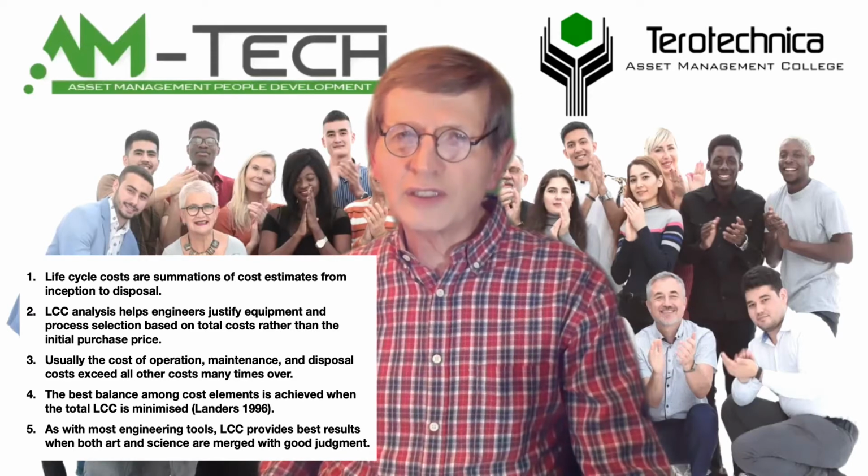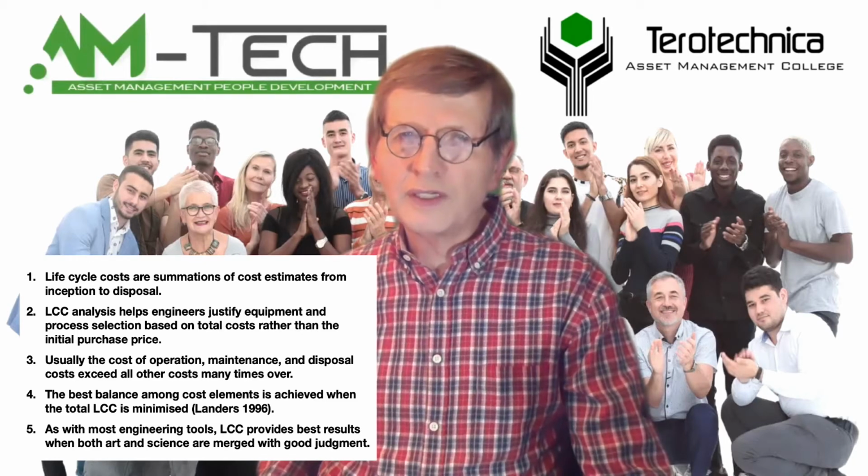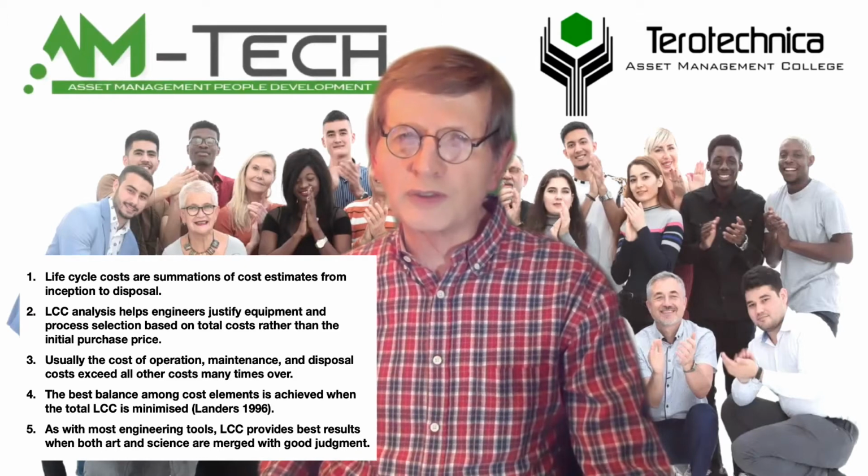Second, lifecycle cost analysis helps engineers justify equipment and process selection based on total costs rather than the initial purchase price. Thus, the total picture is assembled using the purchase price and all estimates and known costs expected over the life cycle. Third, usually the cost of operation, maintenance, and disposal costs exceed all other costs many times over. This is why it would be silly to take the purchasing price only in making the choice between different equipment options.